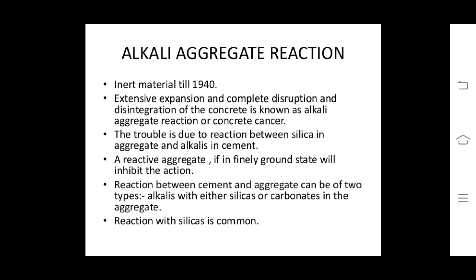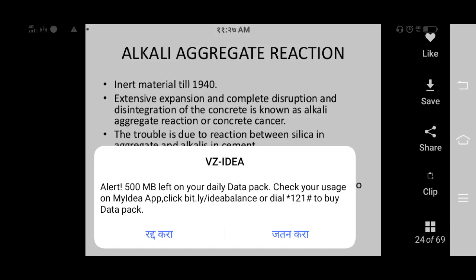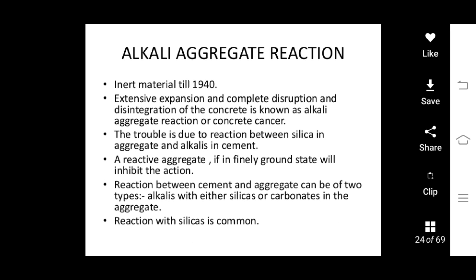Extensive expansion and complete disruption and disintegration of the concrete is known as alkali aggregate reaction or concrete cancer. The trouble is due to reaction between silica in aggregate and alkalis in cement. A reactive aggregate, if in a finely ground state, will inhibit the action.